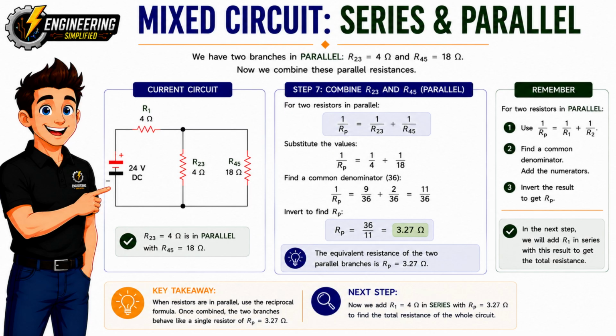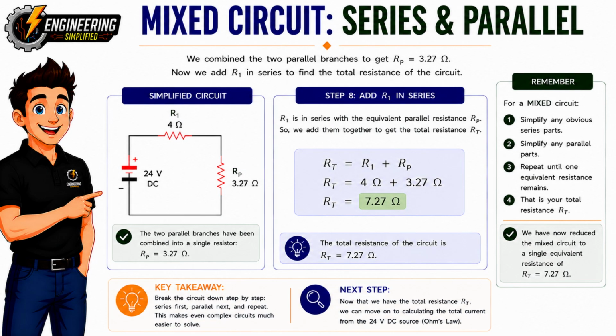We've now replaced both parallel branches with a single equivalent resistance of 3.27 ohms. The circuit is almost completely simplified. In the next step, we'll add this resistance in series with R1 to calculate the total resistance of the entire circuit. We've now combined the two parallel branches into a single equivalent resistance of 3.27 ohms.